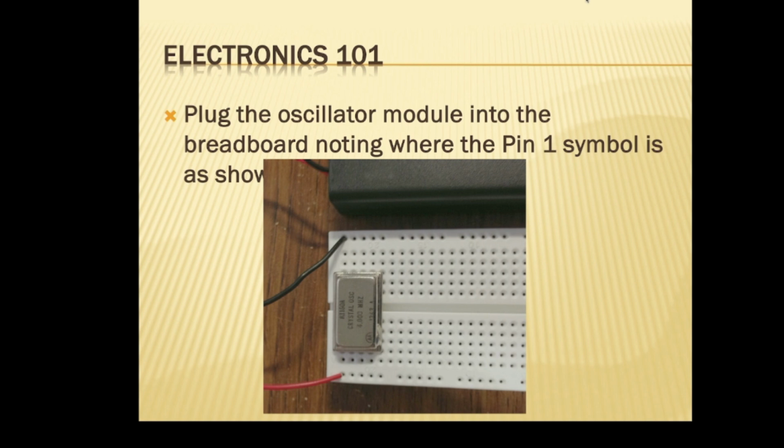Okay, we want a jumper for pin 8. We need another jumper, don't we? Let's get another couple of jumpers. Some of those jumpers just make it easy to get to stuff. Notice the very first line on the handout that says pin 1 is where the little Motorola symbol is. That's where you count from. So you start with 1 there and go down that side, 1 through 7. You've got the other side, 8 through 14.